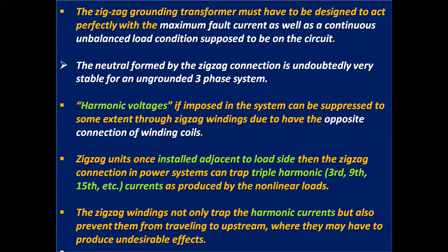The zigzag grounding transformer must be designed to act perfectly with the maximum fault current as well as a continuous unbalanced load condition supposed to be on the circuit.